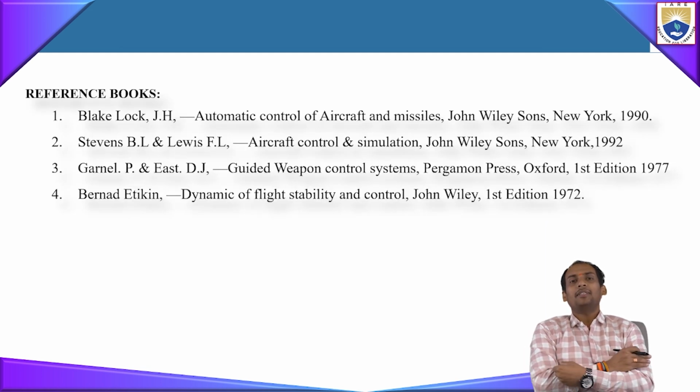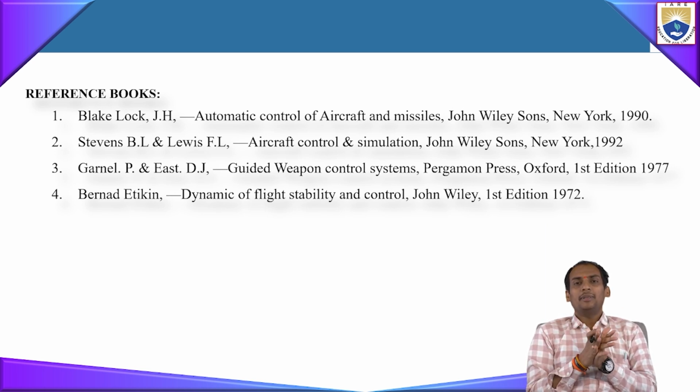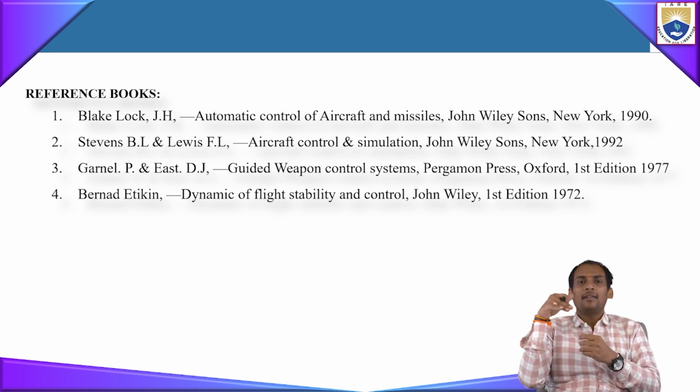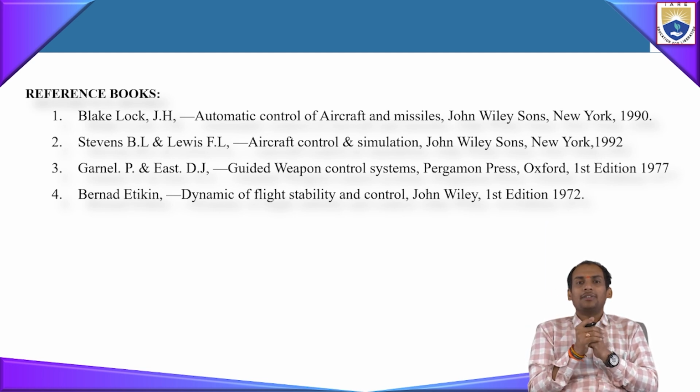Previously we discussed part one, which gives the angular relations, the frequency response with respect to the glide angle, and how to approach the glide angle. In part two we have given the glide slope and automatic flare control, and the transition range transfer function has also been discussed here.